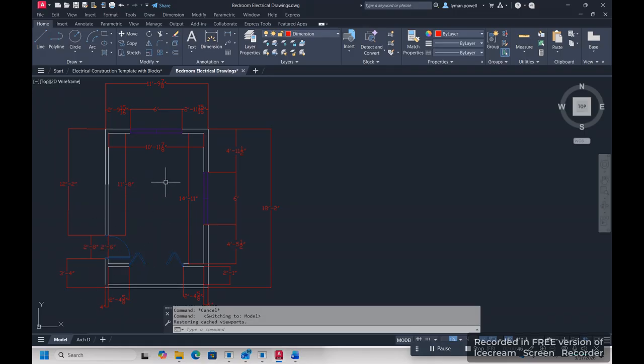I'm going to show you how to do this, and I'm going to let you do some of it on your own, and I'll show you how to do some of it as we go. I'm going to start by just drawing the outside of the outside walls. The outside walls are 6 inches thick. The inside walls are only 4 inches thick. So we're going to draw the outside of the outside walls first. And if you look, it's 11 feet, 9 inches, and 7/8.